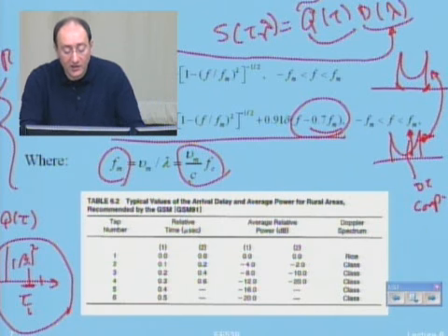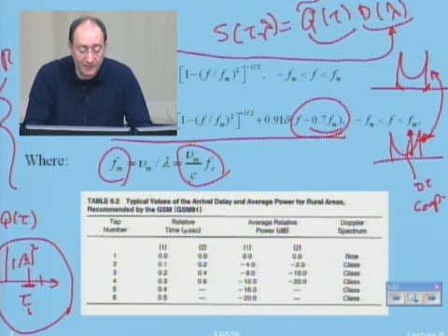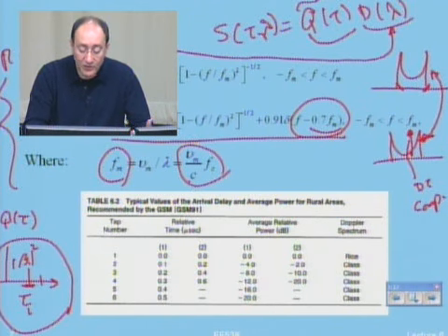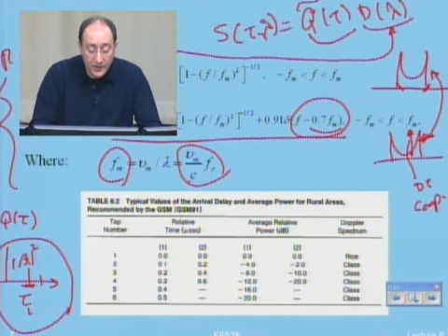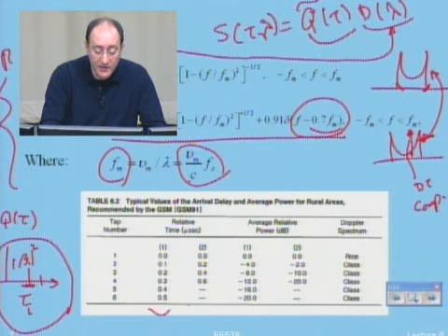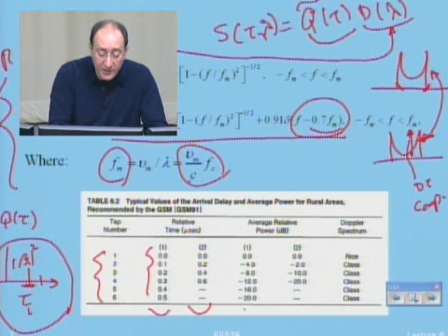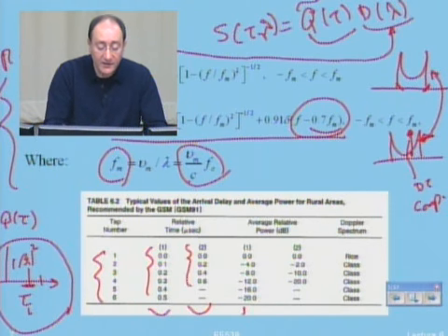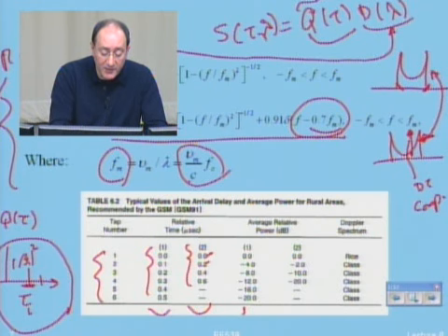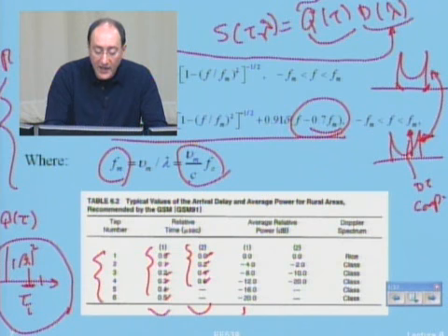Now, this is a typical example which is used by the old GSM models. They give you two possible choices. One is implemented with 6 taps. The other one is implemented with 4 taps. Now, these are the times of arrival of the taps for model 2, the times of arrival for model 1. Okay? And these are the powers associated to each of them.